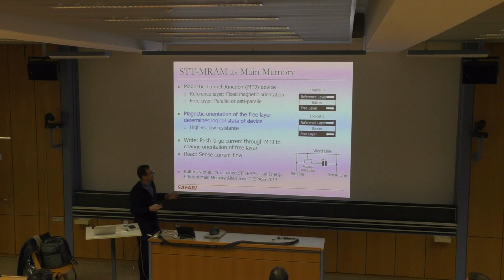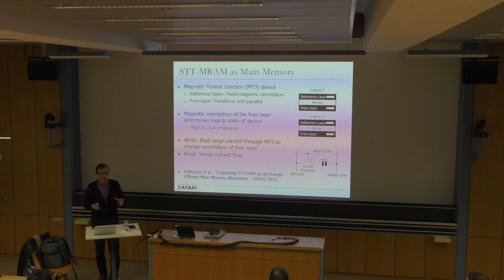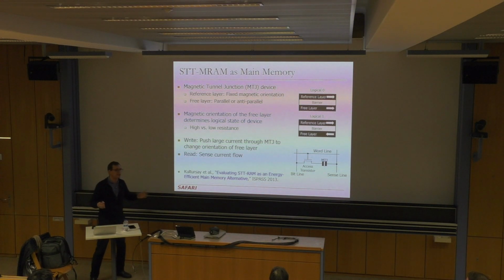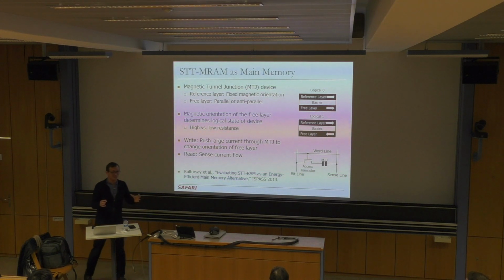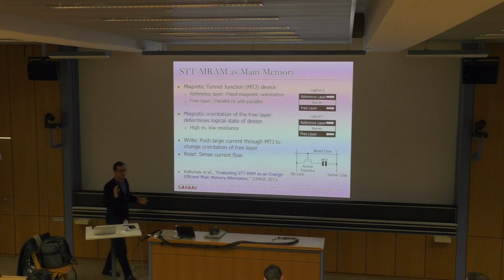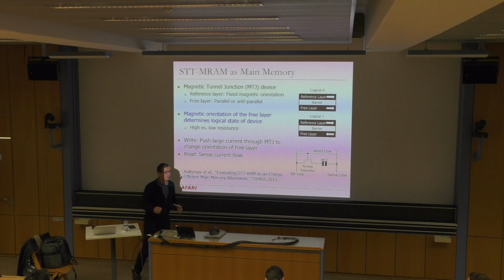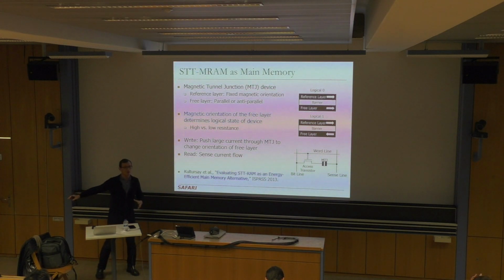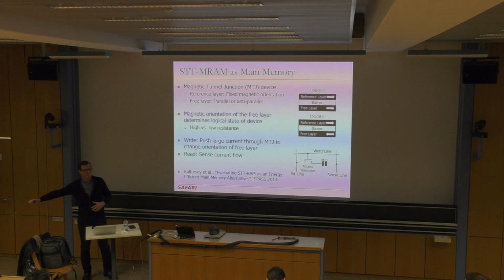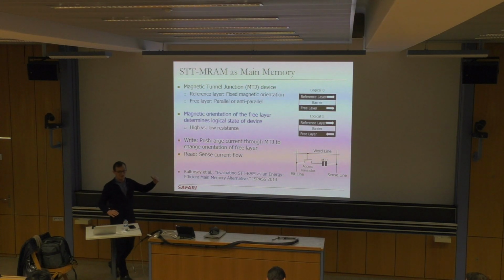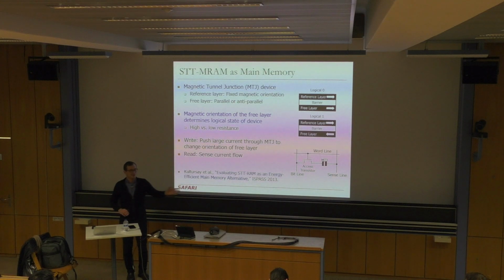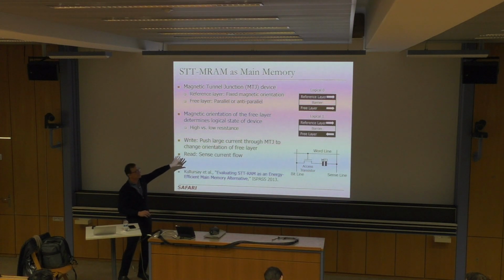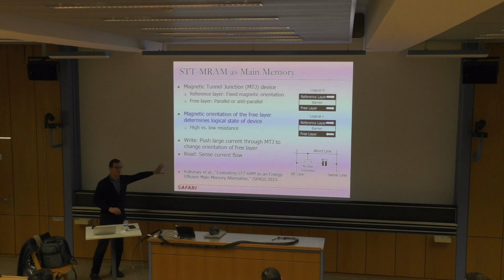this magnetic tunnel junction device, in its current state of the technology, is very large. I mean, it's not as large as this, of course, but it's much larger than a DRAM cell. The size of it is, let's say, 60x of a DRAM cell today. So for it to scale to something smaller than a DRAM cell, it will take a lot of time. Whereas phase change memory size was already, at least theoretically, smaller than DRAM, and even practically with some devices smaller than DRAM. So scaling was much better over there. Here it will take a lot of time, I think, to scale this to something smaller than DRAM.